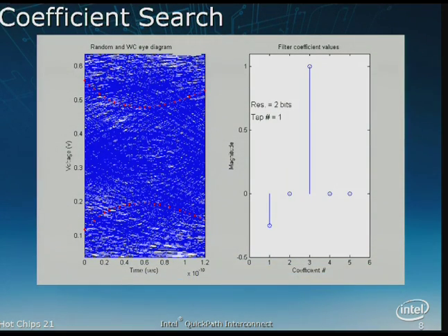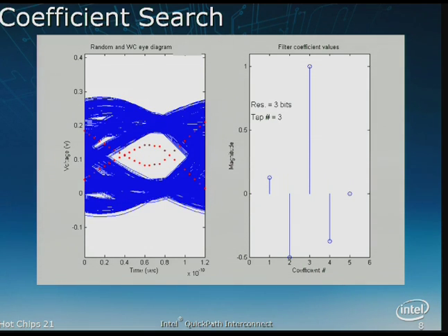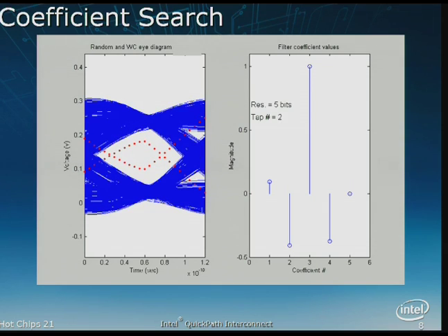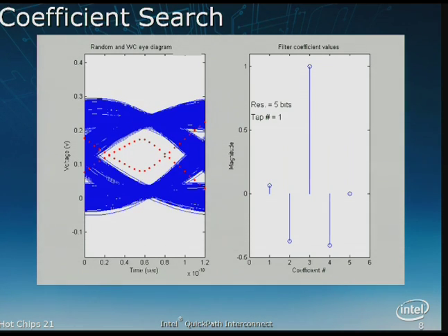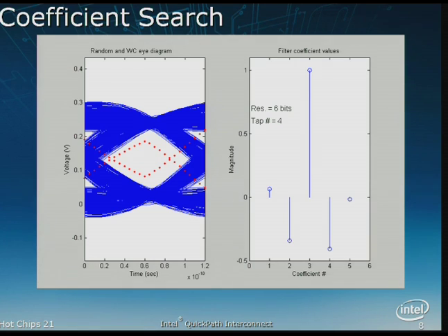Another view of this, of searching for those coefficients, is basically, if you don't know what the coefficients are, the receiver will look at that pulse and see fundamentally white noise. But as you go through training sequences, ultimately, as you adjust your pulses, you'll find an eye for a high and low going pulse. And during our power-up sequences, we do this. The logic will self-determine where that pulse is, along with where the clock edges are and things like that.